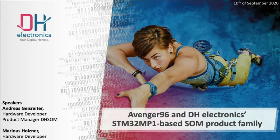Yeah, this depends on the computer you are using. I tried it with my laptop, which is a dual-core i5, and it takes really 22 hours to compile a complete Yocto system. I think you must use a powerful computer, and then it takes 3 to 4 hours to run a complete Yocto build. If you make changes afterwards, it is much faster, taking only some minutes to build. But the first build, even with a very fast computer, typically takes 3 or 4 hours.